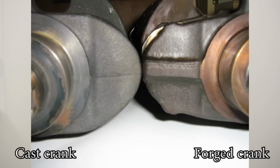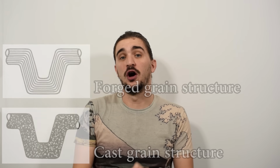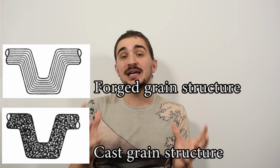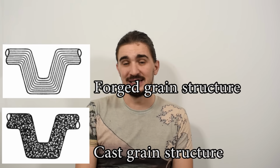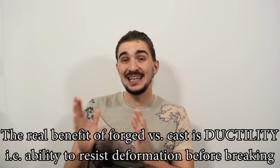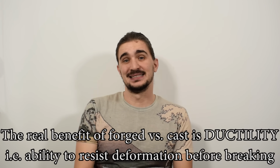The forging process itself significantly compresses the grain structure of the forged crankshaft, and it creates a much more uniform grain structure compared to a cast part. And this means that forged crankshafts are typically not just stronger, but significantly more ductile when compared to cast crankshafts.